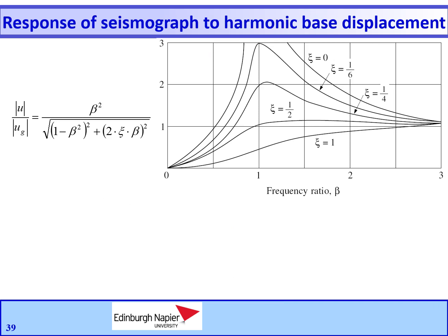We will now apply the knowledge that we got in general terms from structural dynamics to the response of a single degree of freedom system to harmonic ground motion. This is of particular interest for the determination of the response characteristics of seismographs to harmonic-based displacement. It is desired to design the transducer so that the relative displacement u as a function of t measures the support displacement ug as a function of t.